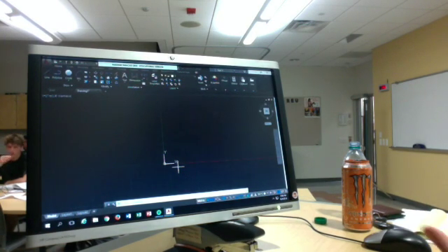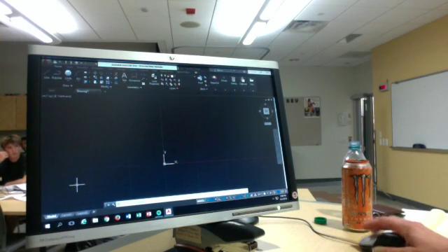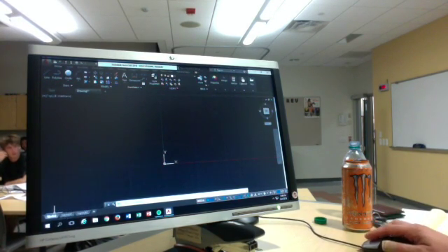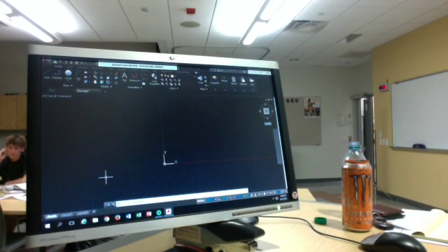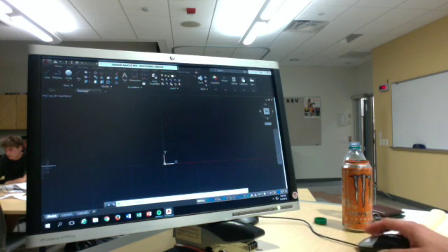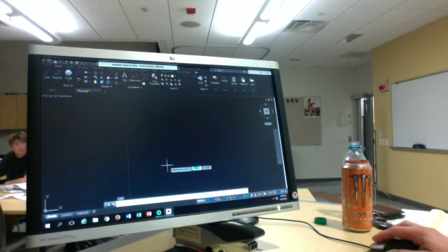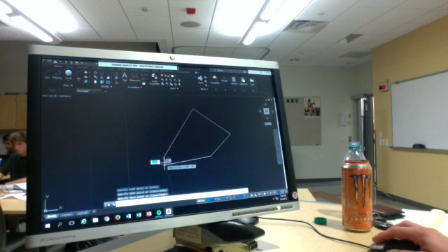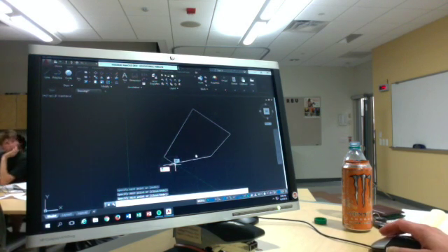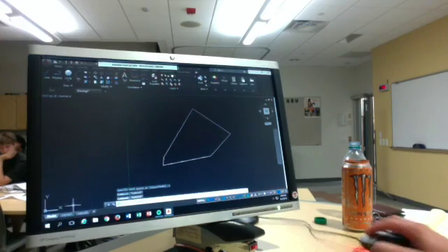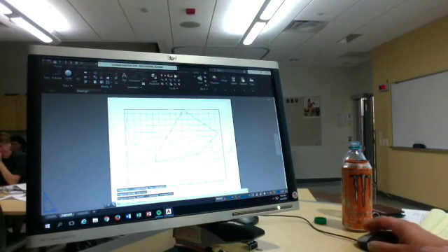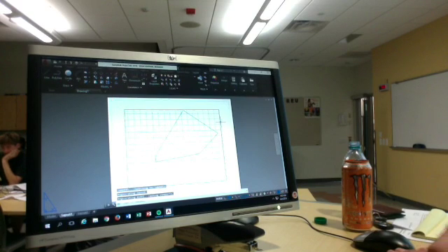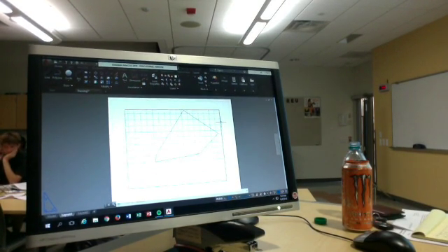So, speaking of sheet sizes, in AutoCAD, as you can see down here, you have model, layout 1, layout 2. Model space is where you actually draw the piece of equipment or building or piece of land. So let's say I have my weird looking thing here. And then when we go into the layout, you have what's called viewports. We're going to cover viewports much later. But the important thing right now is to show you that there's a difference between model space and paper space.